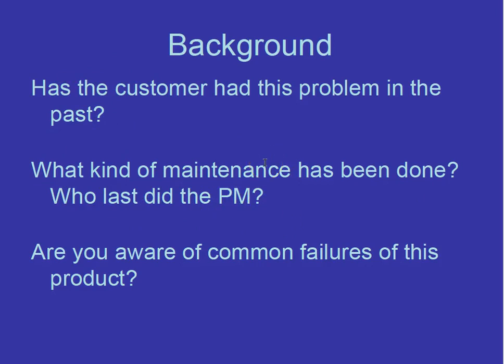Asking these questions is also important because you get to know, for example, if somebody already did the maintenance, then did they change any equipment in the circuit, or did they redo any soldering in the circuit? So you get to know those concerns by asking these questions. So this is important.